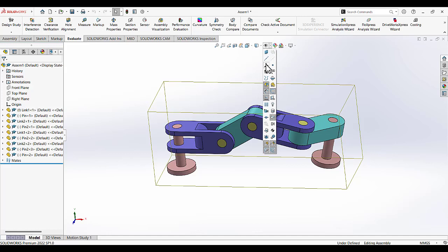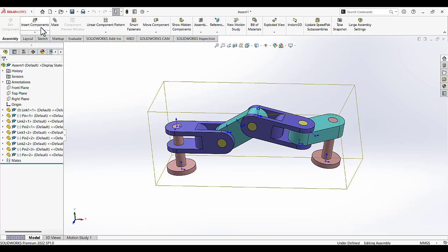So here you have to activate the view coordinate system and the view origin. So you have activated the origin of the component and the origin of the assembly. So when you are inserting the component, this must align with the origin of the assembly. I repeated that many times because that's the most important thing when you are doing this tutorial or when you are doing the exam.